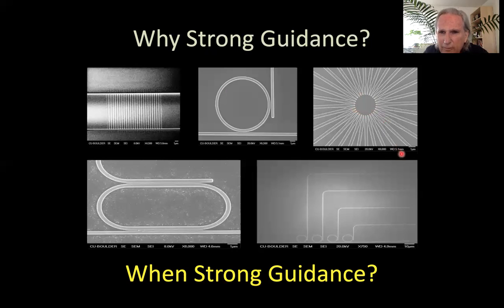Or you can, and again, this could be a multiplexed signal, and this has a rather wide bandwidth. So you could put a multiplex signal and put that multiplex signal to many, many other channels to put it apart. This is a ring type structure. It's like this one, but by changing the parameters on here, I can change the band pass. This is, we've talked about before, a demultiplexer.